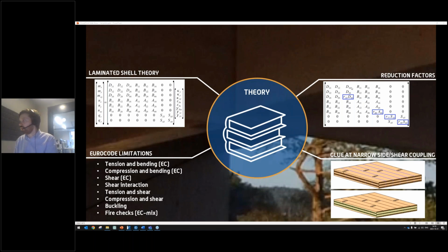applied. So when it says reduction factor R33, that means that this reduction factor is placed in the overall stiffness matrix in position 3, row 3, column 3. And the same for R66, R77, and R88. When we look at the modeling part, I will get back to these reduction factors and show how you can insert them into the software for that specific product.